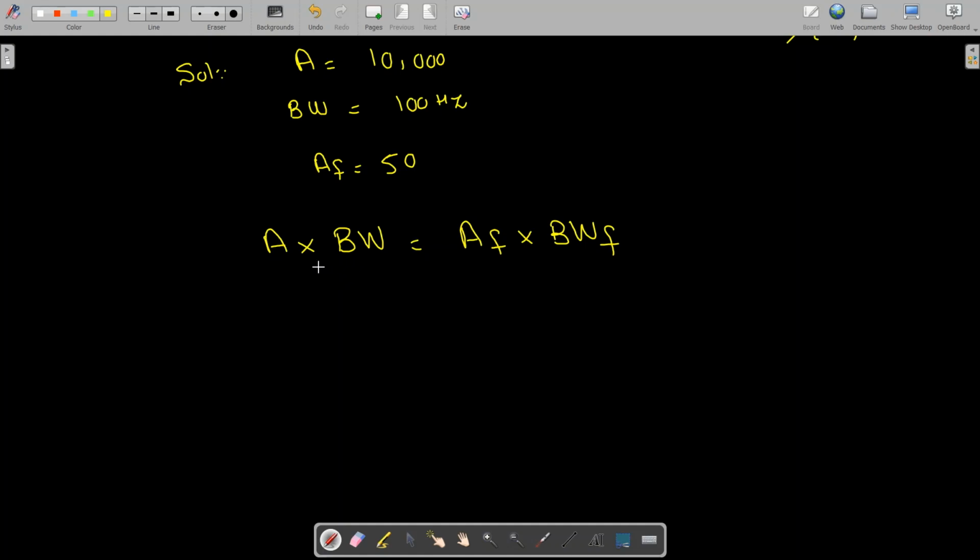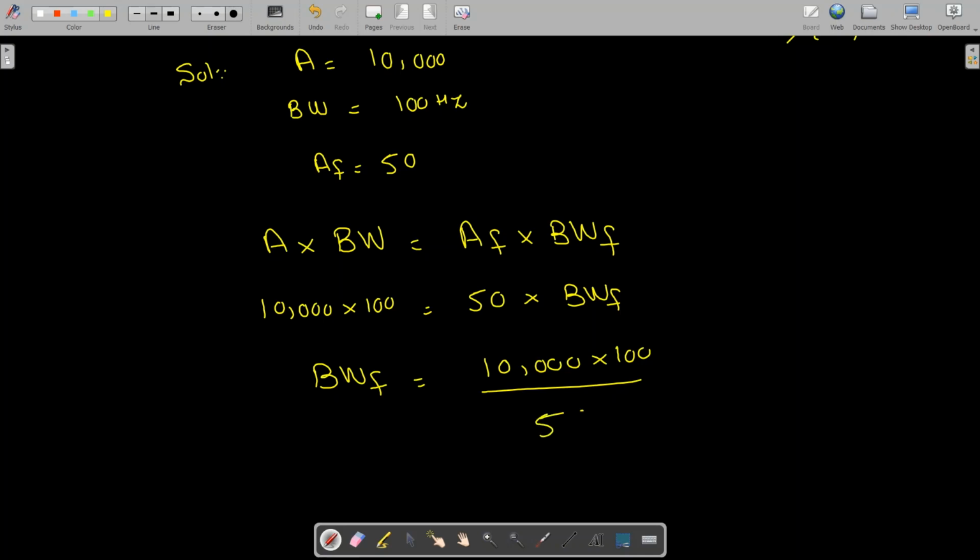Fine. So I'm going to say that A is 10,000. It is multiplied by 100, and we have gain with feedback 50 multiplied by the bandwidth with feedback. This is bandwidth with feedback, that is equal to 10,000 multiplied by 100 divided by 50.